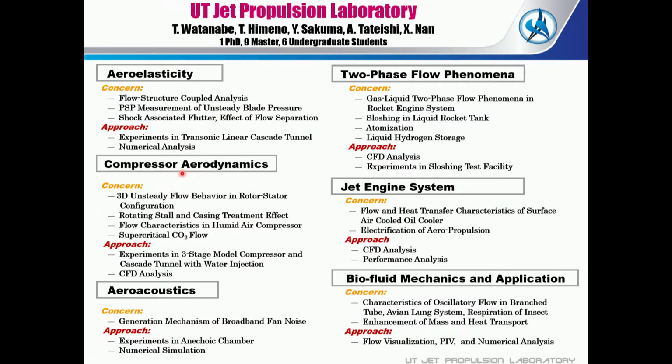And for compressor aerodynamics, we are interested in the 3D unsteady flow behavior in rotor-stator configuration and rotating stall, and the casing treatment effect. Casing treatment is the countermeasure to prevent the rotating stall. And the flow characteristics in humid air compressor. It's a project with industries.